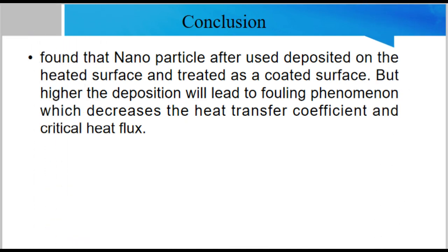Last but not least, for a conclusion, it has been found that nanoparticles, after use, are deposited on the heated surface and act as a coated surface. But higher deposition will lead to fouling phenomena, which decrease the heat transfer coefficient and critical heat flux.